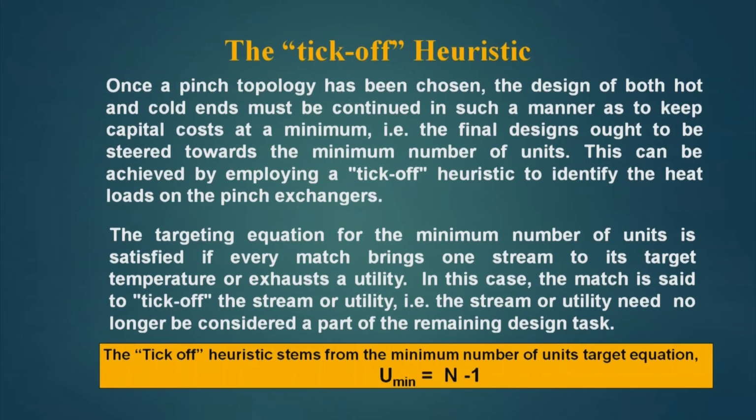Now, let us see a second rule which is called the teacup heuristic. Once a pinch topology has been chosen, the design of both hot and cold ends must be continued in such a manner as to keep capital cost a minimum. We have already said that when we are designing a heat exchanger network, the design should take place in such a way that the cost is minimum.